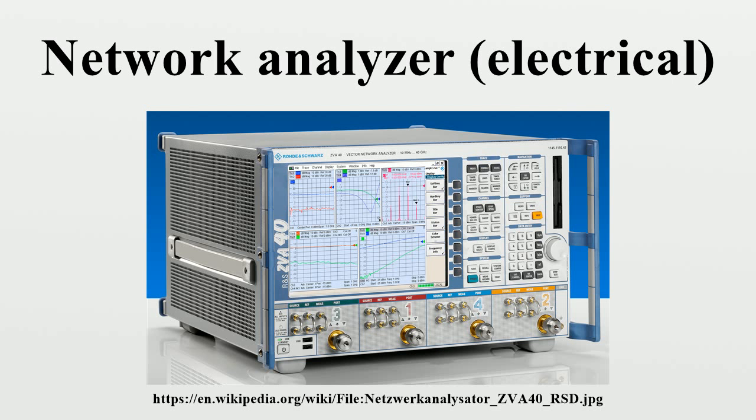TRL uses a transmission line, significantly longer in electrical length than the through line, of known length and impedance as one standard. TRL also requires a high reflection standard whose impedance does not have to be well characterized, but it must be electrically the same for both test ports.